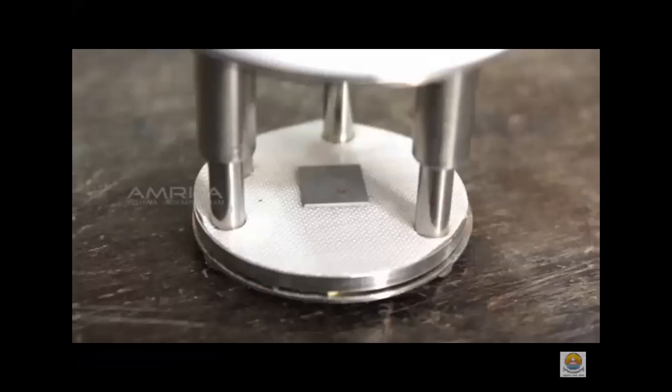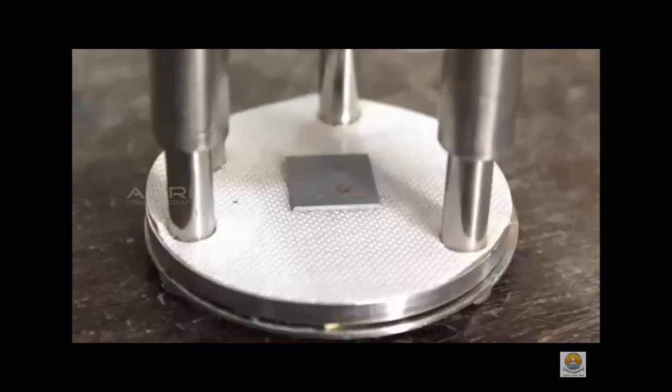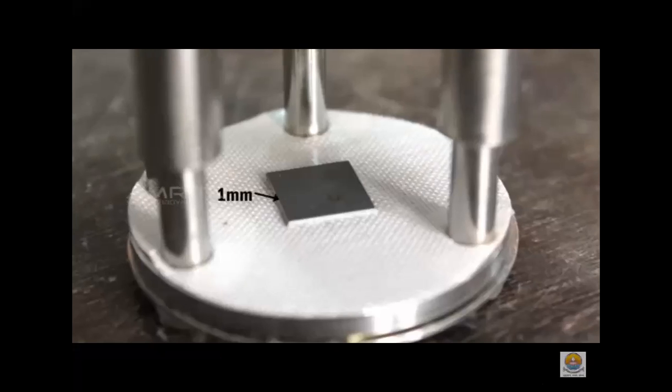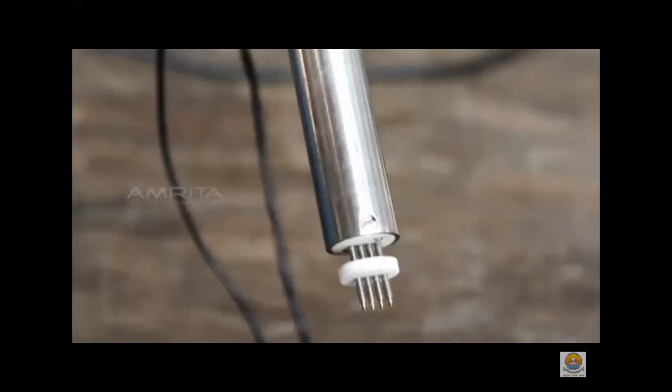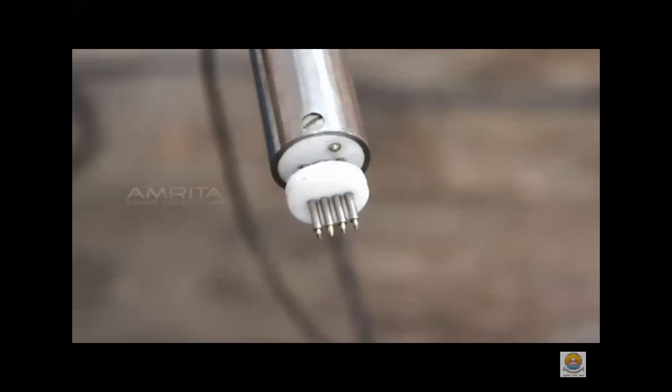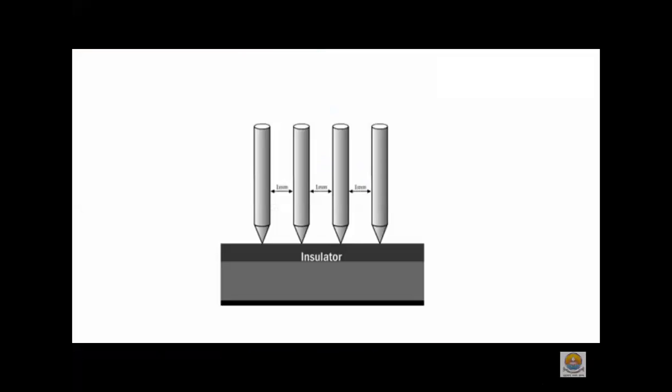A power supply and digital panel meter measuring voltage and current. This method is employed when the sample is a thin semiconducting material deposited on the substrate. In the four probe arrangement, the four probes are arranged linearly in a straight line at an equal distance, say 1 mm from each other.